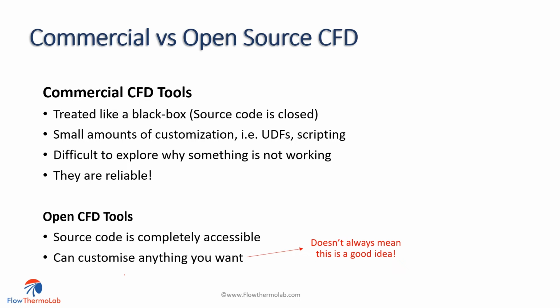So, just because I can go ahead and modify something in the OpenFOAM code doesn't necessarily mean that it's correct. So it's always important to validate what we're doing, and if we have literature available to us online or experimental data to validate against, we should always be striving to achieve what's best and backing up the code that we are developing.